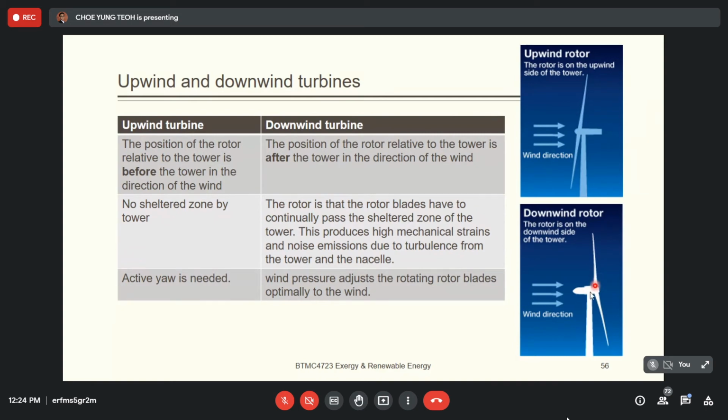Okay, but good thing of this is front part is nutshell, back side is the blade, so that this turbine can automatically face the wind. You do not need active control. Okay, because the blade, if you can imagine, when the wind comes, definitely the blade will go to the back. If the blade is lightweight, it will automatically go to the back. You don't need to face the direction. You will always face to the back. Okay, this is the nature of it. You will push away whatever has high resistance to the back. Okay, now of course the blade has higher resistance than the nutshell, so it pushes to the back.